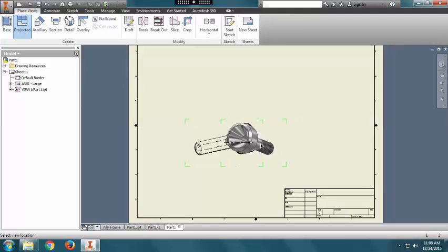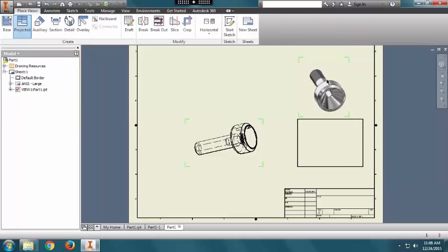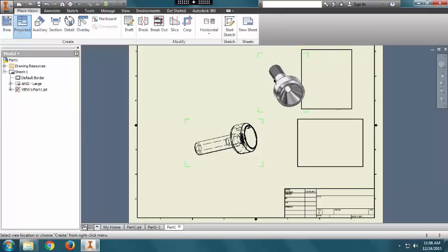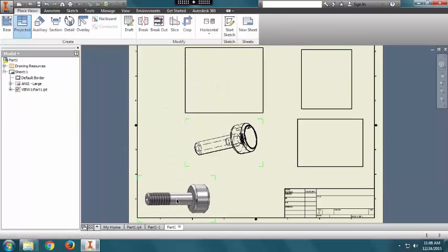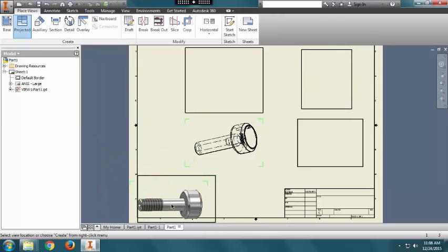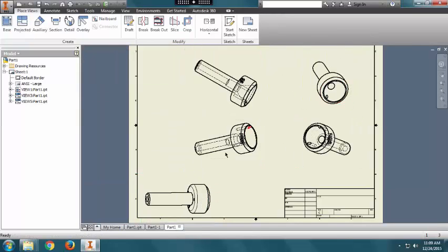So there is a section that has been created. So this is according to the position the part is in your drawing file. So let's drag this aside, and that will give you the other views. See, just project it to the direction you would need. Just click, there are boxes created. So after you create the boxes, just right click on that and use the create option. So there you have all the components created.